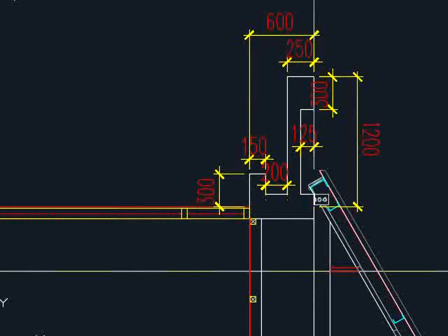or you will need to provide the longitudinal reinforcement bar, a minimum size of Y12 mm, and also beware of the secondary reinforcement bar, as you might have a concern of failure here due to the weight of the gutter. Therefore, make sure you provide sufficient reinforcement bar at 2 layers here in order to resist the members from falling down.